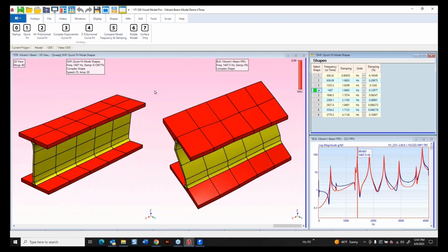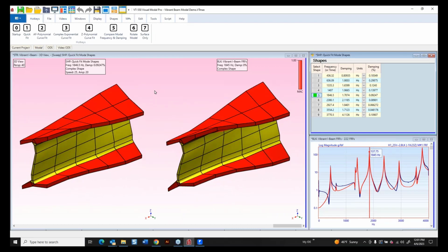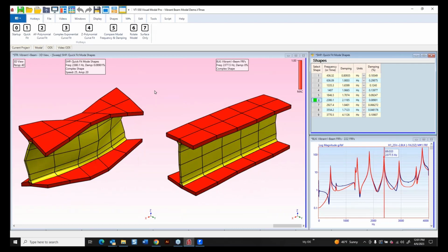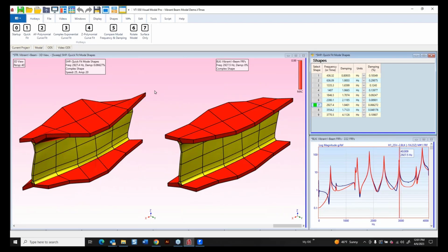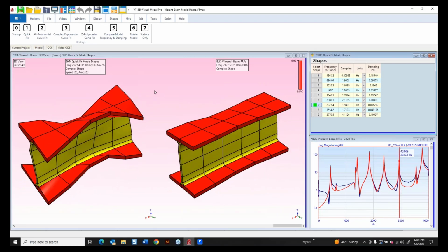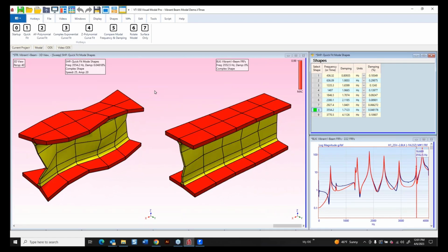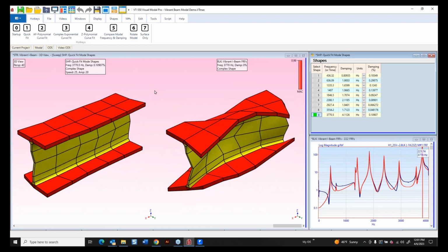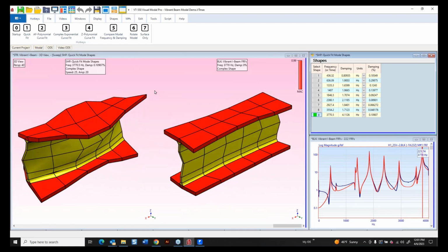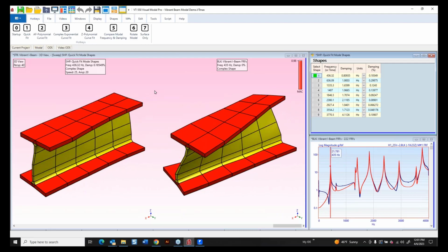And we don't measure one row or column of the FRF matrix, so we can move. We don't need long wires. So that's something we covered before. We'll come back to that. And we showed coherence. So you normally want good coherence between your force and your response, or if you're using a reference, between your reference and your response signal.